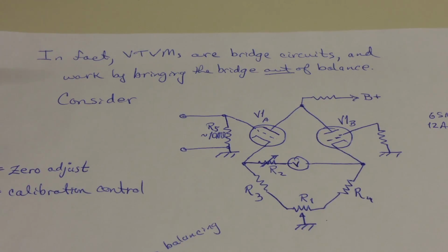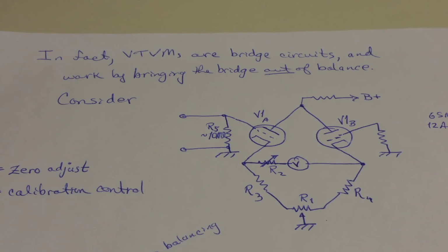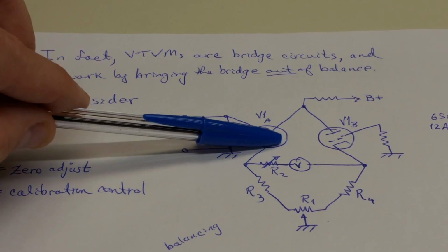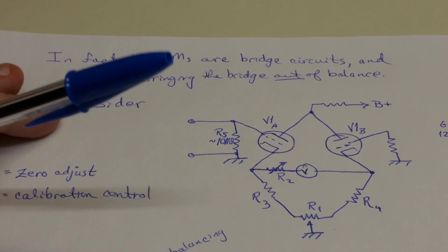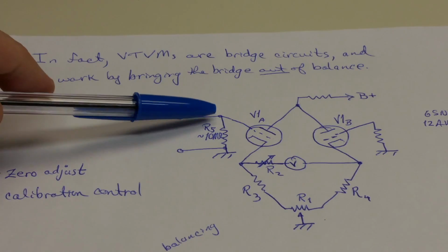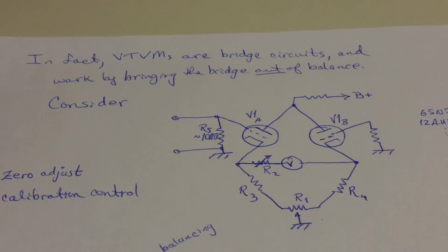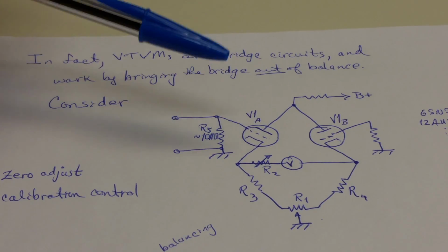All right, so this VTVM is in balance when there's no voltage applied. If I apply a voltage now to this grid, and here I've written a resistor through here is 10 megaohms, but in general this is a voltage divider network that's either 10 megaohms or 25 megaohms or whatever your particular VTVM input impedance is. You have a positive voltage showing up on the grid here.